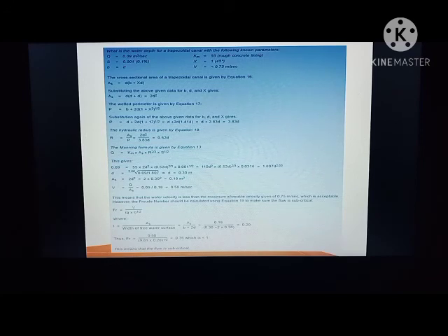The hydraulic radius is given by the equation R is equal to area over perimeter, which is equal to 2D squared over 3.83D, which is equal to 0.52D. The Manning formula is given by the equation Q is equal to K_m times A multiplied by R raised to 2 over 3 multiplied by S raised to 1 half. This gives 0.09